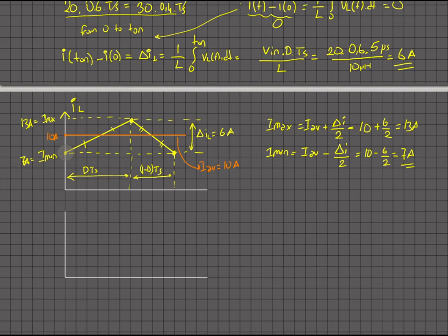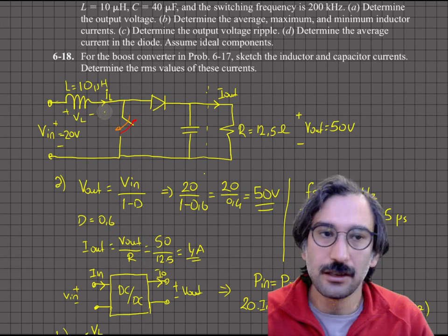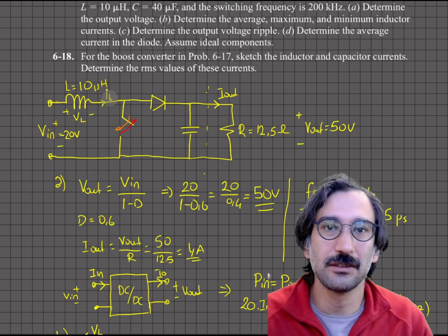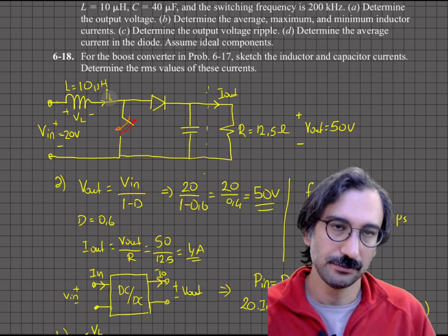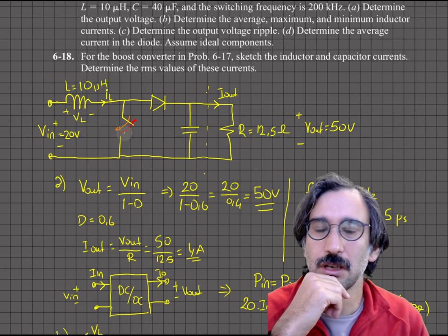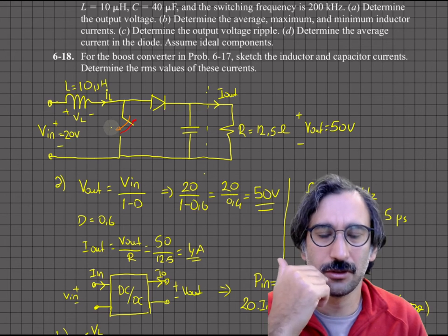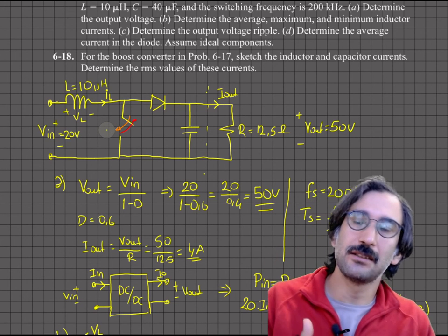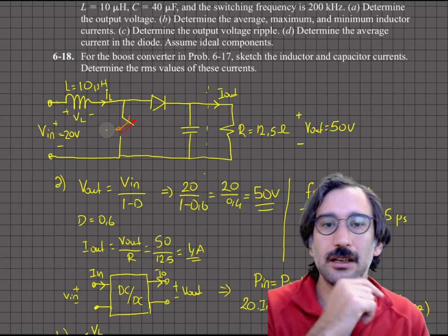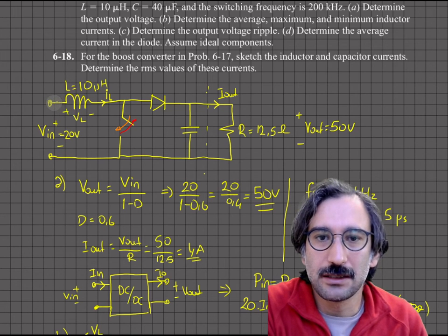So we are seeing from our input voltage source, when you just turn on that switch, we are not dealing with what happens if we just start when the inductor current is 0. That's a problem we investigate in the 4th year power electronics course, but in this course we just assume steady state operating conditions. In the steady state, we assume you started the converter and it's already working, and the steady state for that boost converter starts from 7 amps.